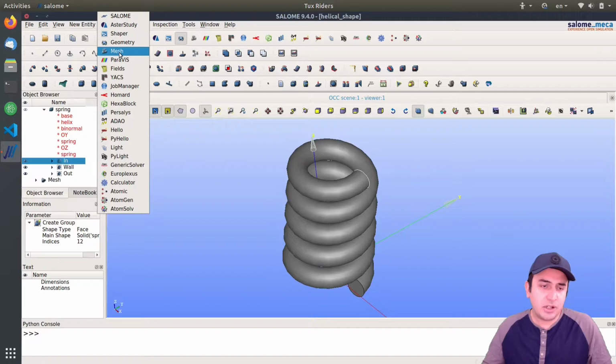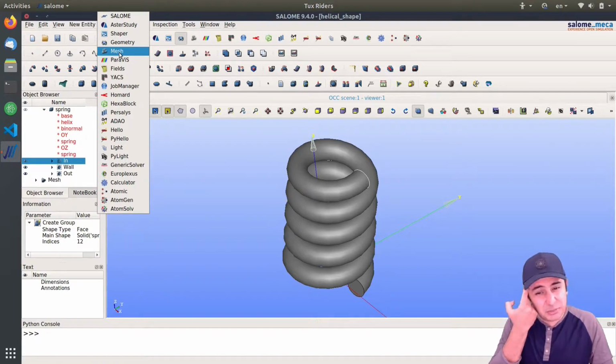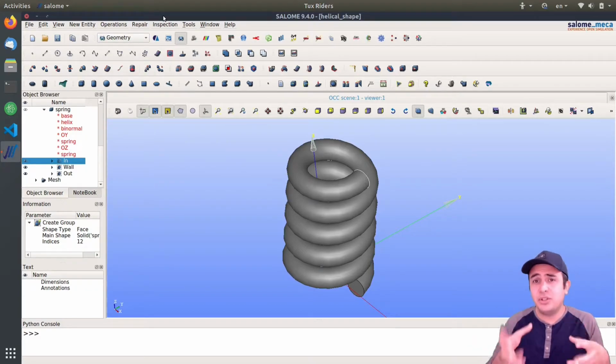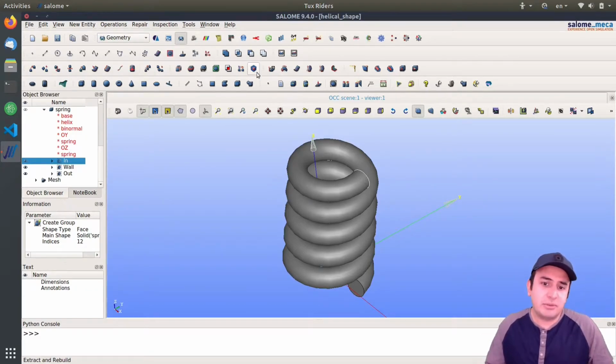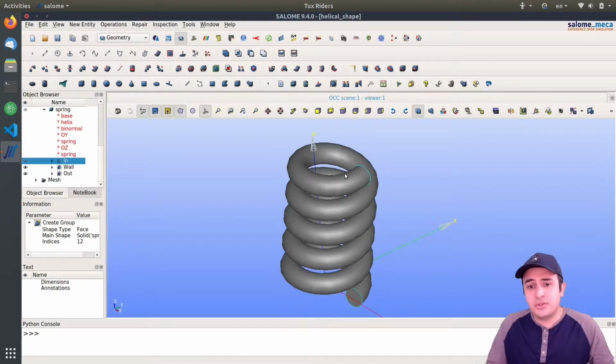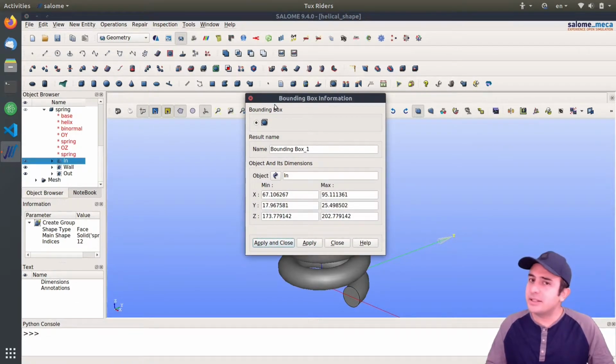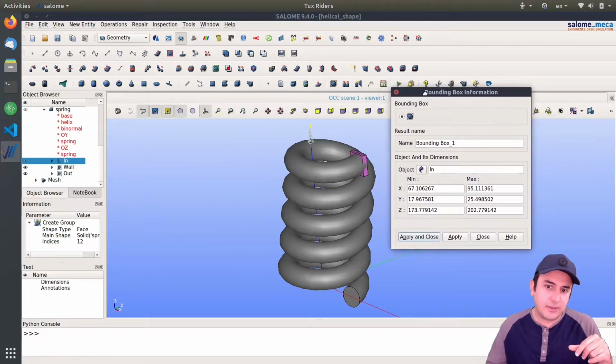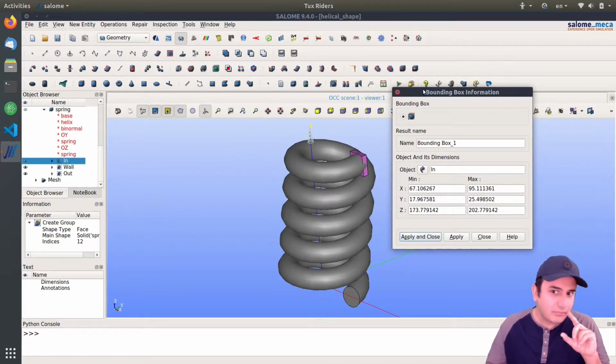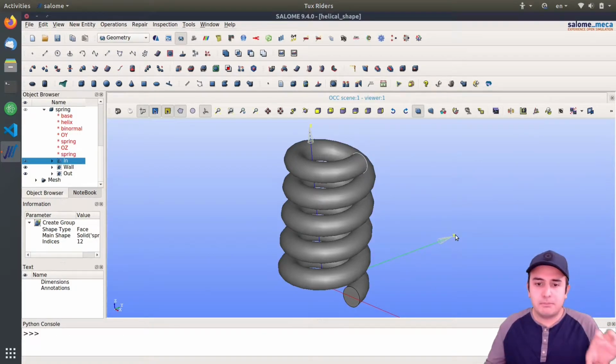Cool. So we go to the mesh module. We did what we did in the Elmer video. In the video where we solved this problem using Elmer, you saw that I rescaled this geometry into something smaller because this is actually a very big geometry. But since OpenFOAM has quite stable solvers, it's very easy to deal with these geometries, even in this size. What we need to do is actually define a big, let's say, coefficient for diffusion. That's what we need to do. And then you will see that OpenFOAM is very handy, very powerful in solving these kinds of problems.